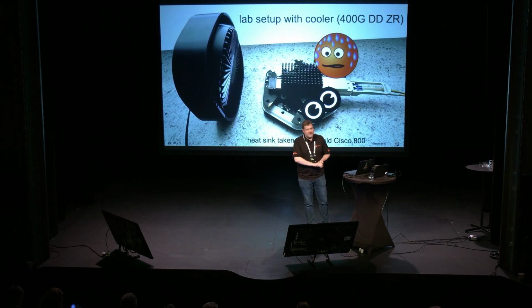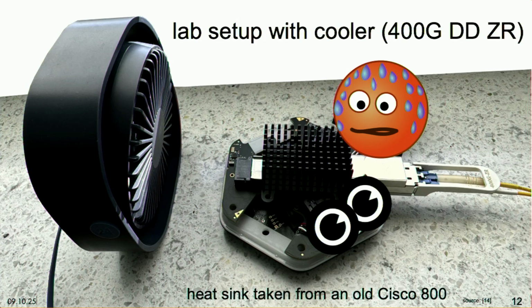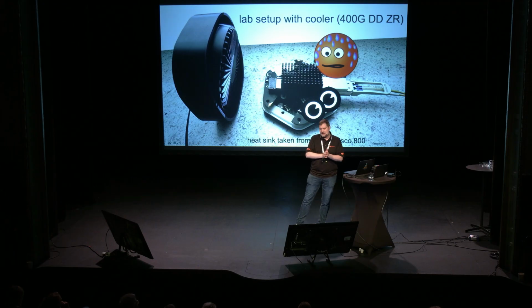So here we have a coherent transceiver, another setup I tried. This presentation is about comparing coherent. We heard about coherent transceivers in the morning and direct detection. To recapitulate a little bit, direct detection uses an eye diagram, as I explained. The coherent uses polarization effects and phase shifting.